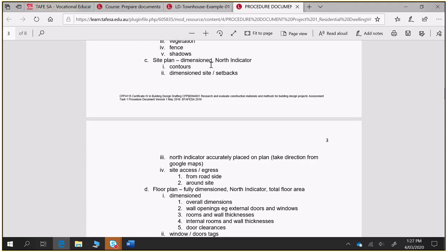So, site plan, you want to keep your contours on there, except for where you've put your driveway or your building pad or something like that. You want the contours chopped out from that. You want to show your setback and dimension. Typically, what you want to do on a site plan, and I apologise for those at home who can't see this, but we've got a site plan here, we've got a building on that. You want to dimension only twice to where that building is.